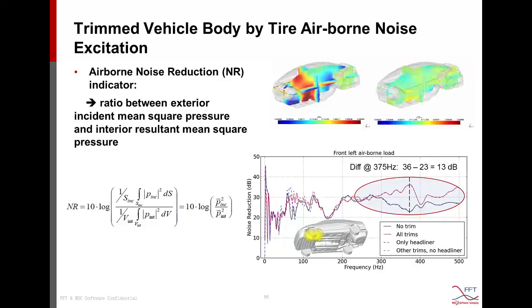And this example shows that actually at this relatively lower frequency range, 300 to 400, we already have this effectiveness of the porous material, which is physically not strictly due to absorption of the acoustic waves by the porous material, but due to the compression of the porous material by the neighboring plates on each side.